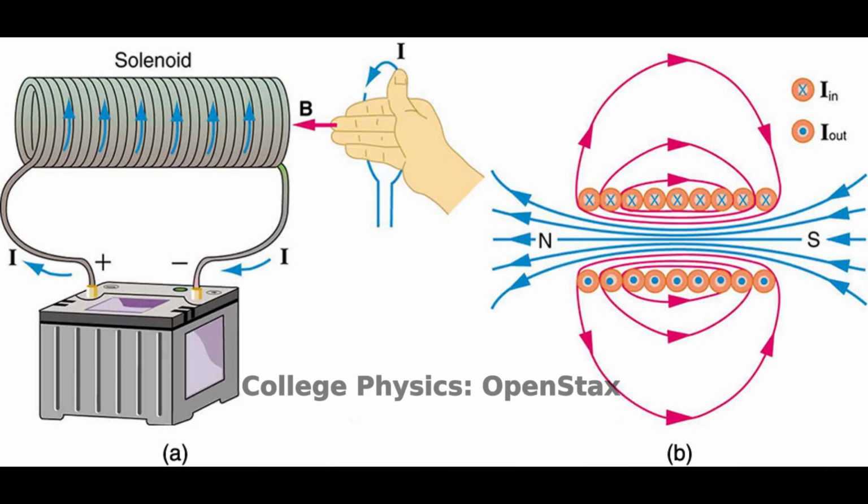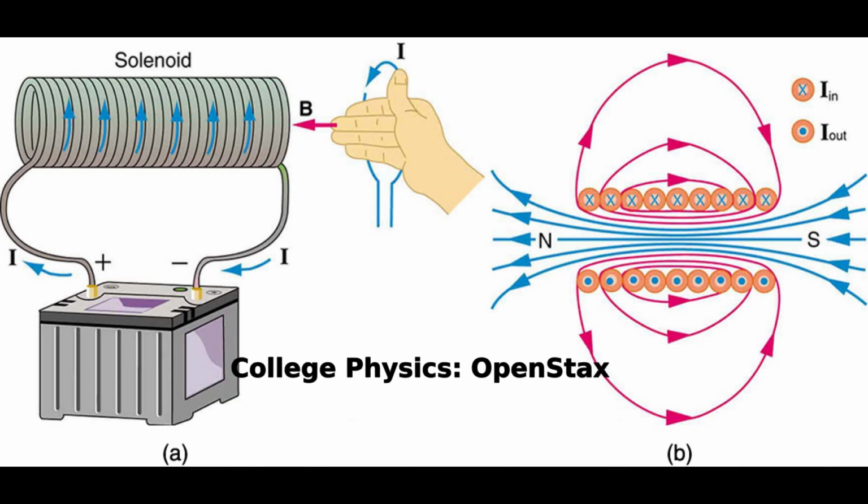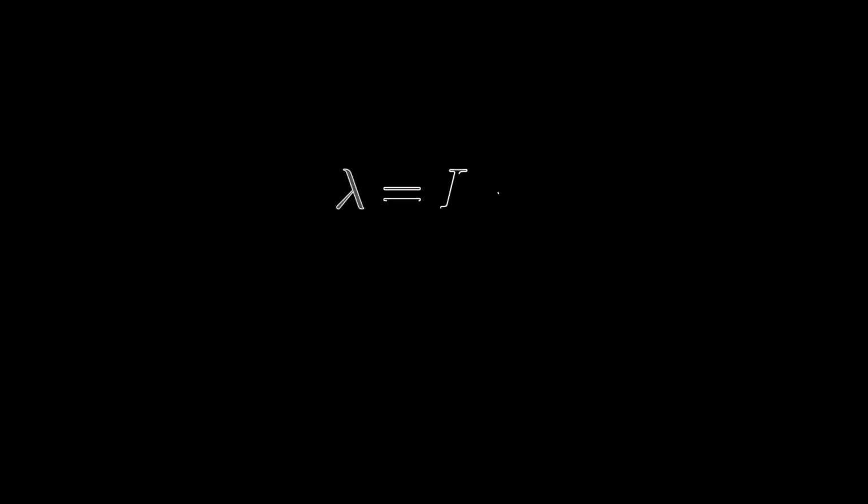As we know, passing current through a coil generates a magnetic field through the coil. So we can model the flux linkage passing through the coil as the inductance multiplied by the current. Lambda equals L times I. But for permanent magnet motors, there is another part that contributes to the flux linkage, and that's the magnetic field generated by the permanent magnets. So lambda equals L times I plus psi. So that's the flux linkage.